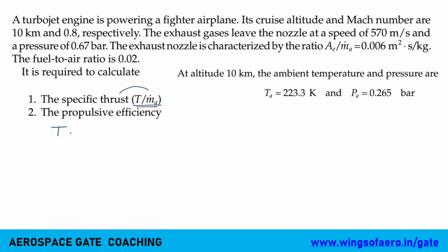If you know the general formula of thrust, what is the general formula? Thrust equals mass flow rate times VE minus VI, plus PE minus PA into AE. This is the general formula.